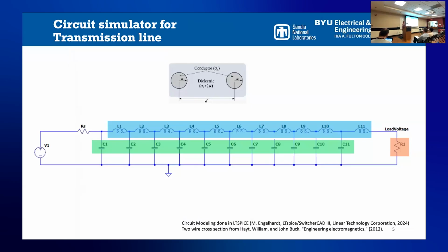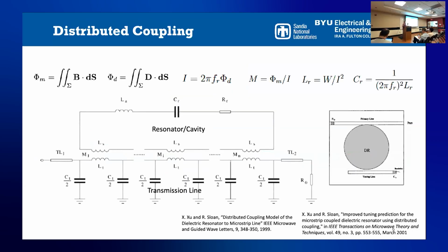The elements outlined in blue are called inductors, and they model how electric current on one wire can perturb magnetic fields to cause current on the other wire. The components outlined in green are called capacitors, and they model how charge on one wire can affect the electric field to change the charge distribution on the other wire. The component outlined in red is called the load. In an actual application, that will be replaced with a big complicated circuit. When your circuit is inside a cavity, the cavity mostly interacts with the long wire parts of the circuit.